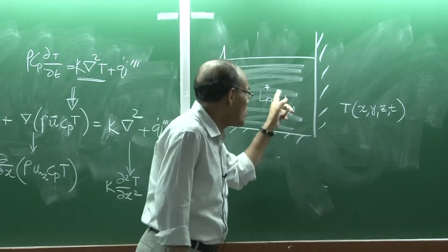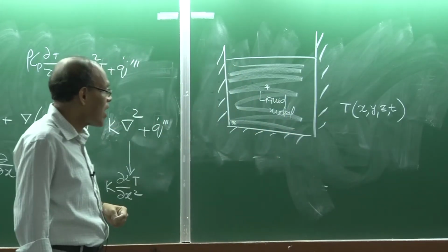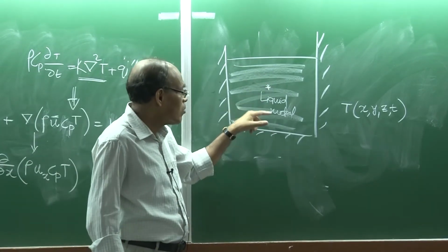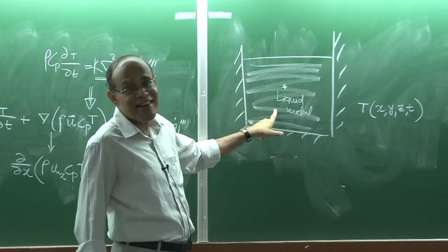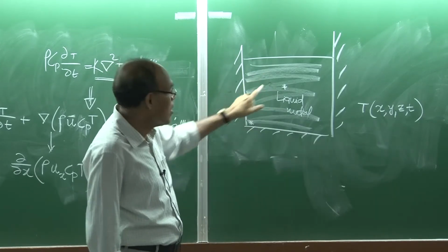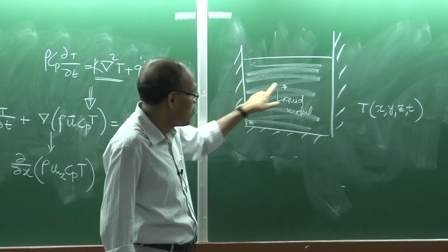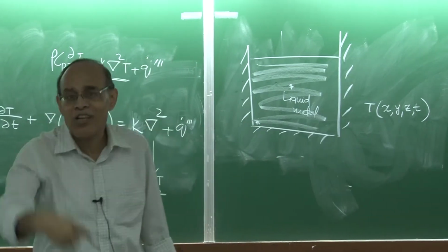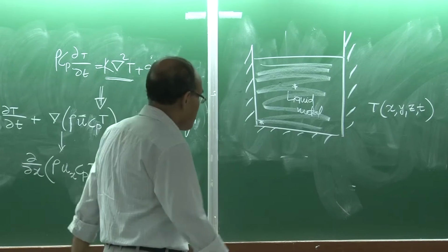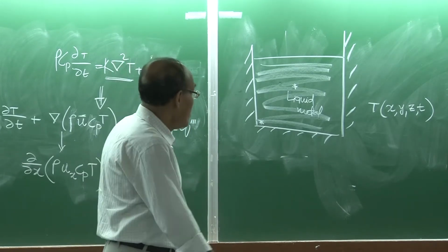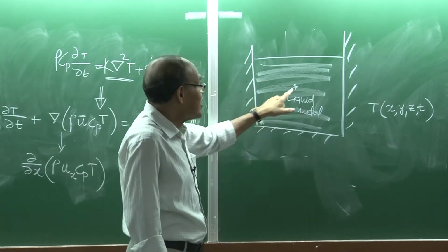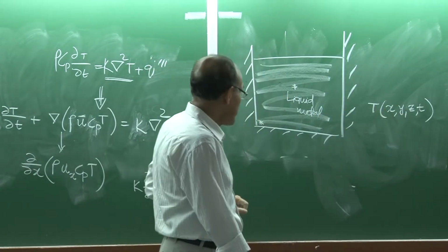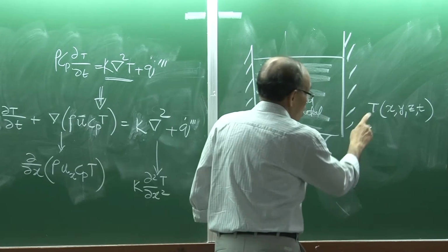This temperature distribution in the system, I want to introduce one term before I proceed further, will itself cause, even though there is no external stirrer here, it looks like a stagnant bath, but the moment I have a differential temperature between the locations, there is going to be a convection current, which we call a natural convection current set up in the system, thermal buoyancy. Because the density of the metal is a state property, and it is a function of temperature.